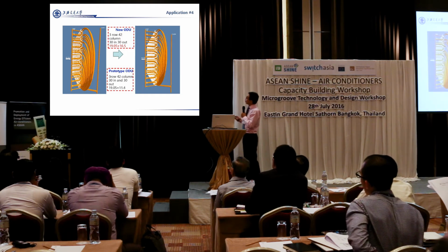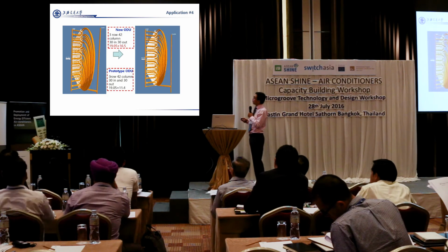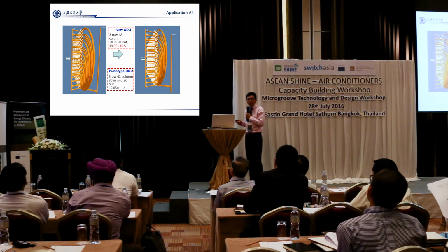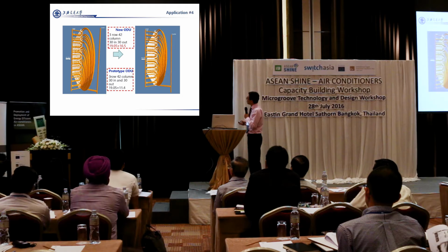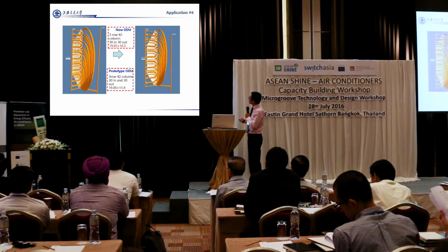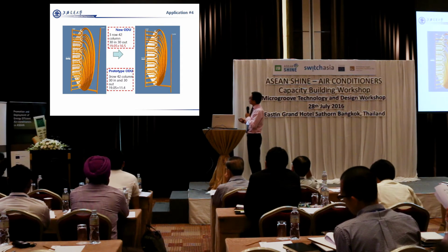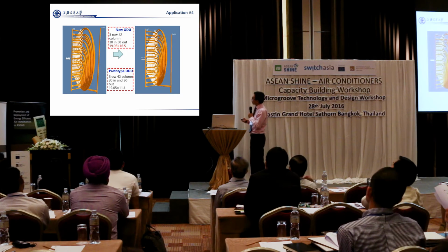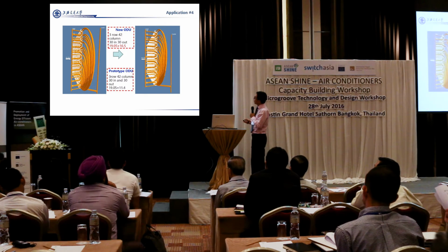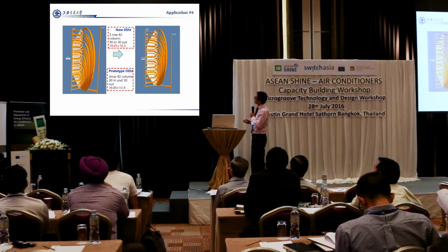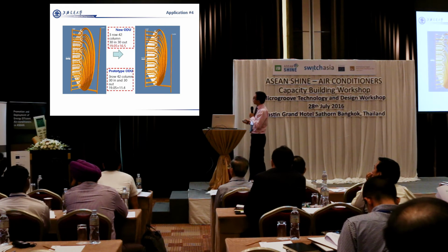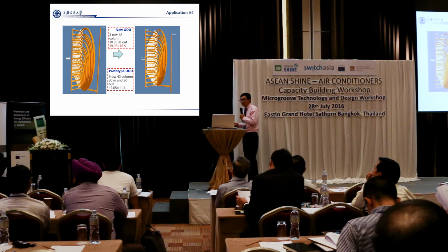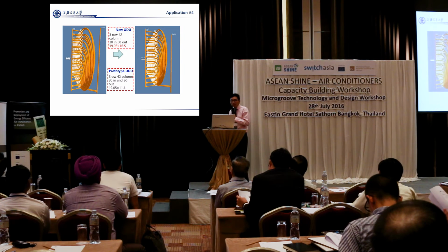It has 3 rows, 42 columns, and 3 in, 3 out, with a lot of branches. Our prototype ODU is also 5 millimeter. The fin pattern is 19.05 by 11.4, and the original one is 7 millimeter.